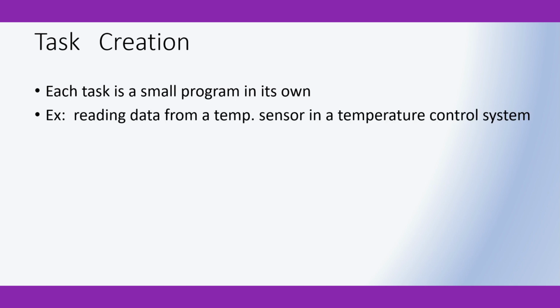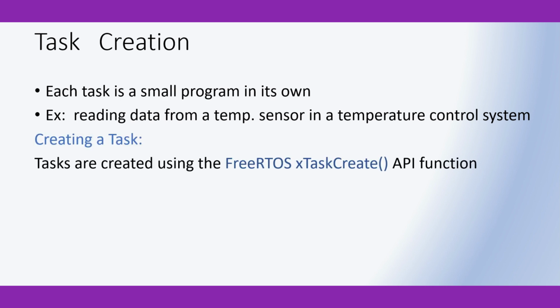In this video, we will learn how to create tasks in FreeRTOS. Each task is a small program on its own, for example, reading data from a temperature sensor in a temperature control system. Creating a task: tasks are created using the FreeRTOS xTaskCreate API function.